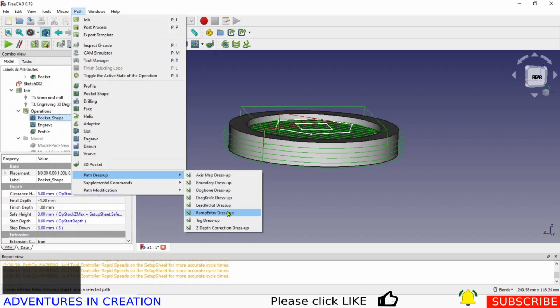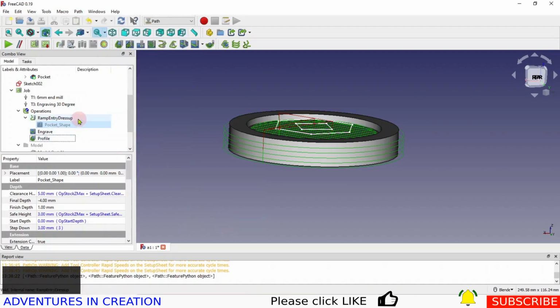entry dress up. What that's going to do is cause it to move as it's coming down. And the idea of that is so I'm not dwelling in one spot, because when you dwell with the cutter and you bring it down, even though these cutters can cut on the bottom, they move just a little bit. They'll sort of circle a little bit, and they'll cause it to cut a bigger hole than you really wanted. So by using the ramp entry, it'll ramp down, so it'll be moving in the XY axis as it goes in the Z axis. So it's as simple as just saying ramp entry dress up.